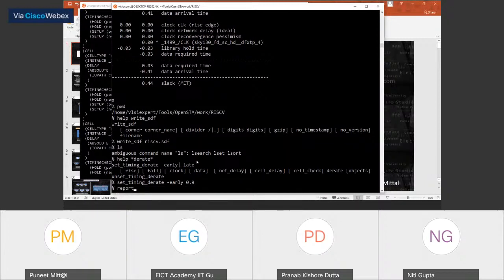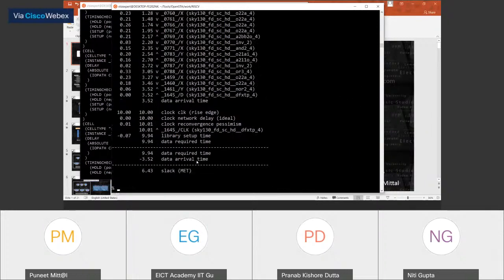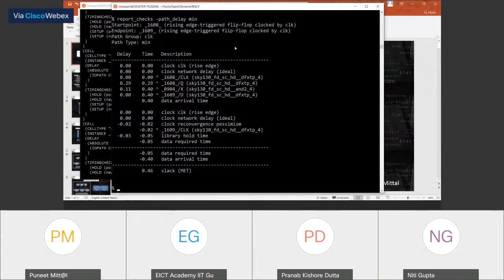Now let's do report_checks. Let me do report_checks with minus path_delay min. Okay, some number came.